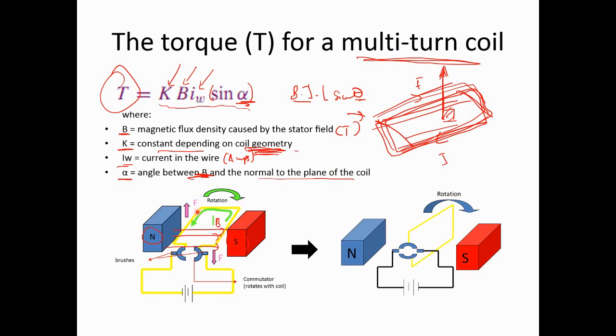And if you look at the portion on the left, the current now circulates in the opposite direction. It comes from inside the paper towards our direction, right? So with this direction of current and the same direction of magnetic field, we create a force that goes upwards, right? So on the left, upwards, and on the right, downwards. It means it creates a rotation in the clockwise direction, right?